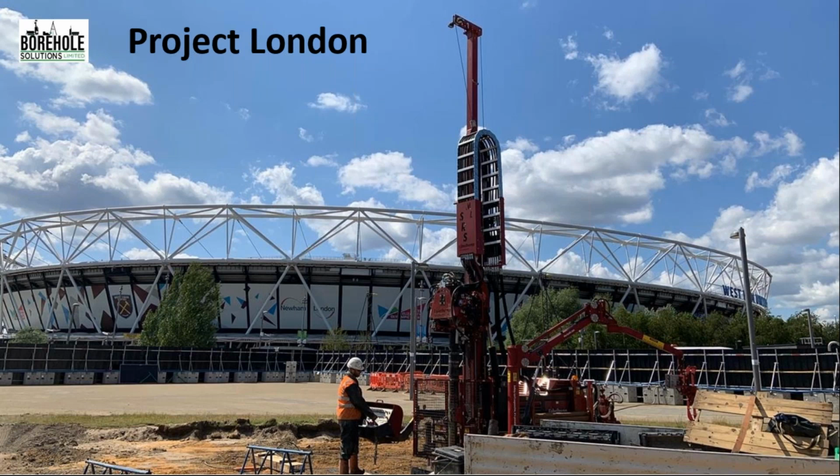Mainly GI. Yeah. Okay. So you have been drilling cable percussion for a long period of your life. 22 years, so a lot of experience in that. How does sonic compare to that, and what is its place in the market? If they had sonic when I first started, when I was 15 years old, I wouldn't have a bad back now or dodgy ankles. That's the fact. Because it takes all the manpower, the manual handling out of it, when you're lifting everything up with the arm on the side of the rig, screwing it together. So that's one plus.